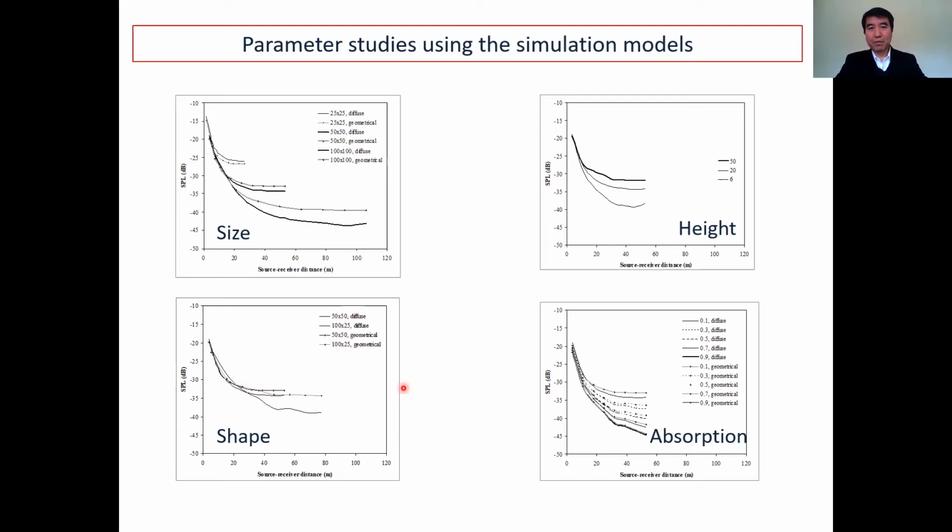And if you don't change anything in the dimensions or physical property, and just change the boundary condition, for example from a brick wall or concrete wall into a brick wall full of vegetation, which is more absorbent acoustically. A brick wall typically has an absorption coefficient of 0.1. If you increase the absorption coefficient, for example by adding vegetation, to 0.9, then you have a very big reduction.